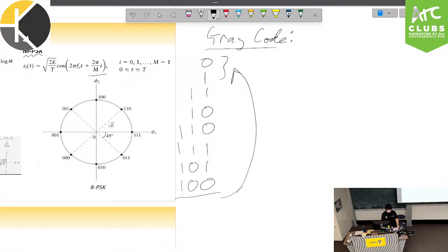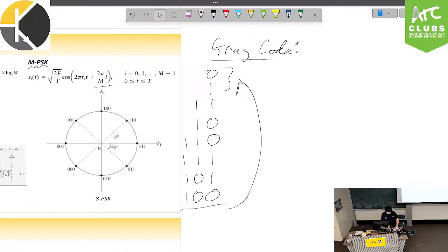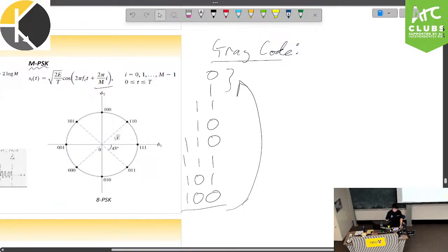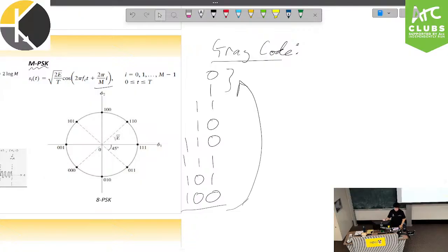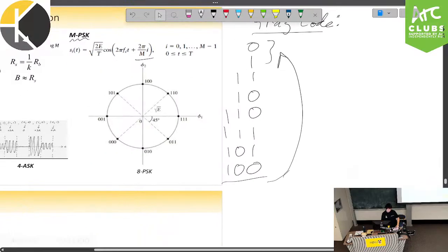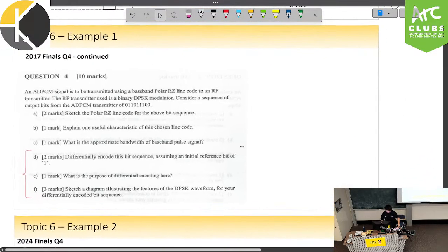You can take notes. The steps were do 0, then 1, then add a 1 on the end and reverse, add a 1 on the end and reverse, until you have as many bits. Okay, so that's one way you can do gray code. It always works. Trust me, please. But yeah, the idea of gray code is you're only changing 1 bit at a time, which this permits. You get as many values as you get in binary, which makes sense. And yeah, does that answer your question? Fantastic. All right. So back to the question.